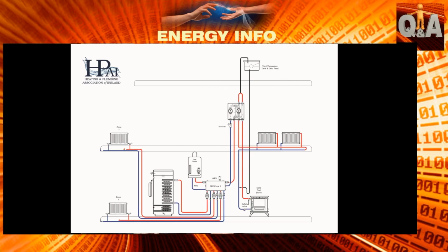But it's critical to remember the energy link or any secondary system should never be allowed to draw energy away from the stove until the water reaches 55 degrees. So the stat within the energy link would be set at 55 degrees.